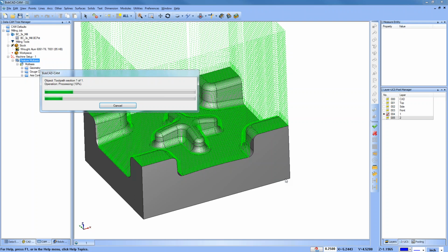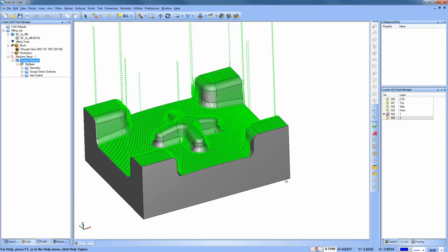Okay, there was a question that Sean had with fixed parallel Z. There's still maybe some scallops depending on the size of the bit. Does this somewhat eliminate the scallops? No, I don't think so. The scallops that you're going to get are going to be based off the slope of the surfaces you're selecting and some of your step over settings. So, using either Z level or planar,